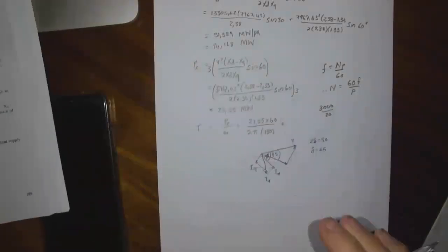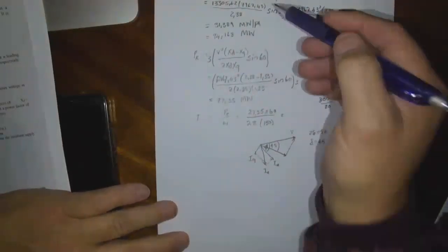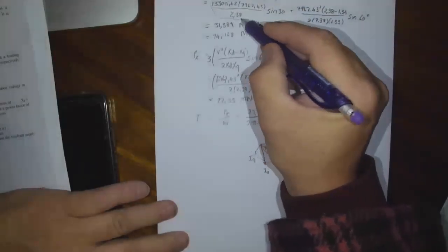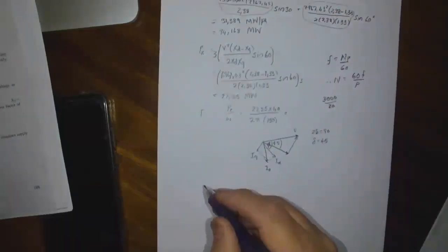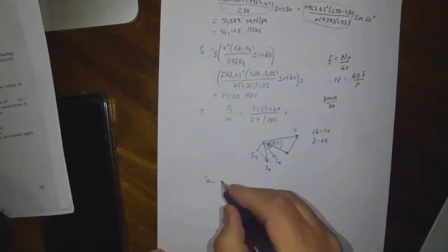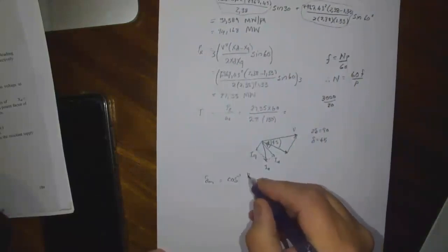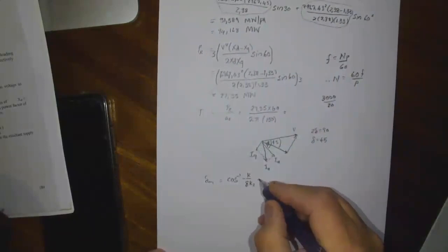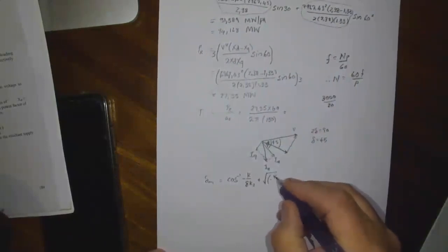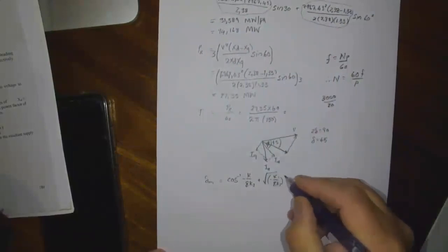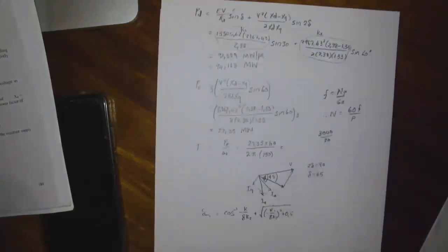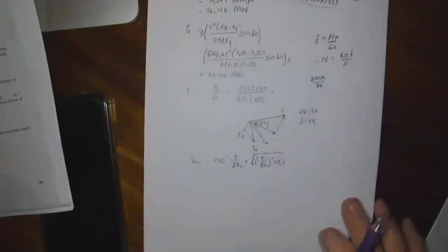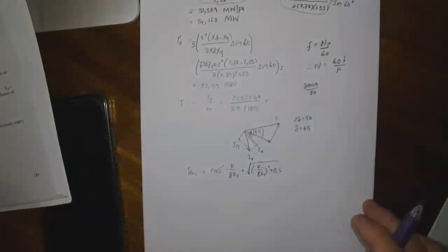Oh, okay. All right, then something else. When you calculate P develop, that part, write it down. And the same with this part, because you're going to use it when you calculate delta max. This must be arccos of K1 minus K1 over 8K2 plus the square root of (minus K1 over 8K2) squared plus 0.5. So this part here is K1 and that is K2. So once you've got that, write it down. Otherwise, you have to calculate it again and again and again.